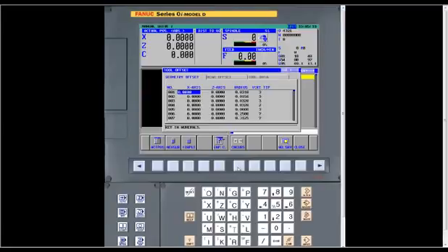All right. Question here. When you touch off the tools, normally do you have to input them again, or will the iGuide pull them into the setup? Oh, yes, yes. Because this is the same data that's on the CNC side. It shares that information. When you measure a tool, it will pick up the data from your standard tool offset screen. Okay.